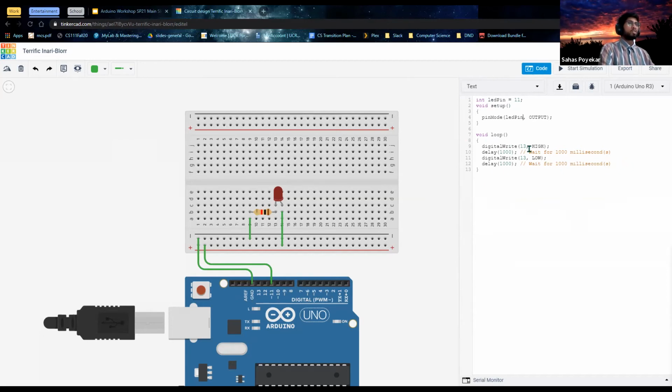All we have left to do is write inside of our void loop to determine what is going to be happening with our LED. So I'll delete all of this code and start fresh. Since we're working with analog signals this time, because we're working with the PWM, instead of using digital write, we'll write analog write, and we'll write to LED pin, and initially we'll have it set to 0.